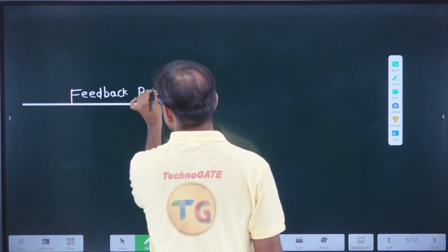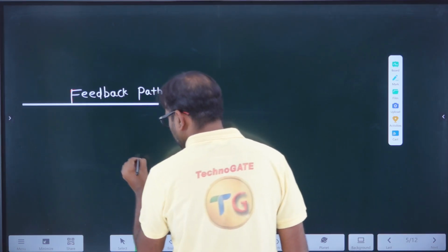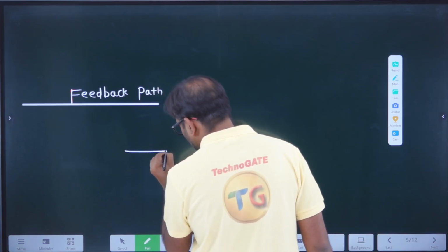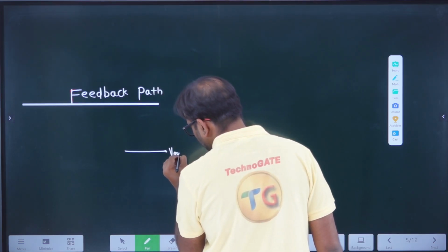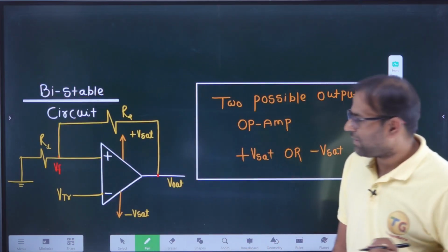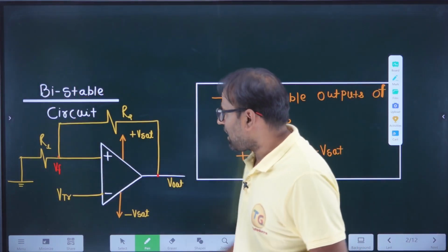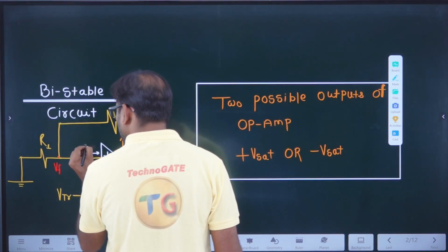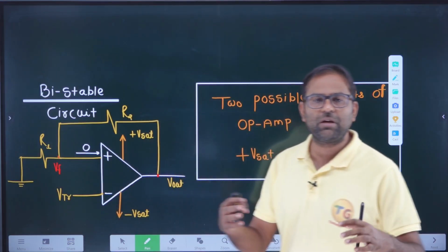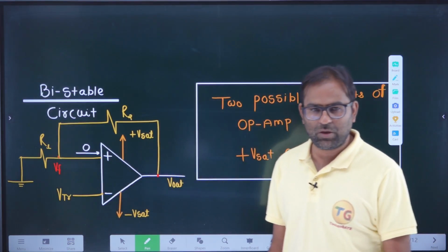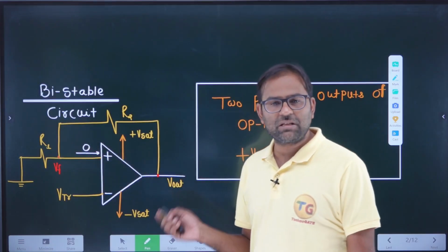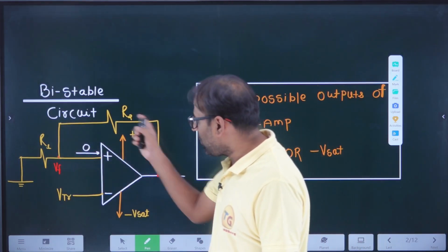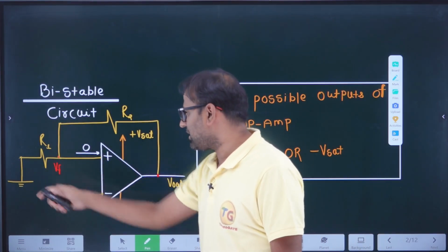And can I say here the feedback path is given by, here we are having one output, that is V out, and R2 by R1. Always remember, we are using ideal op amp, and ideal op amp will not accept any current from the network. So input resistance is infinite, that's why it is 0. So you can say V out is connected to the ground via this terminal.